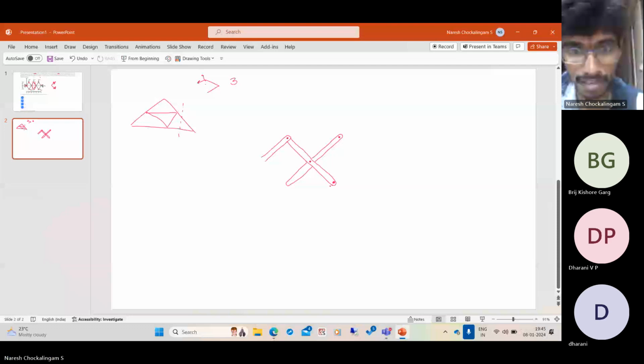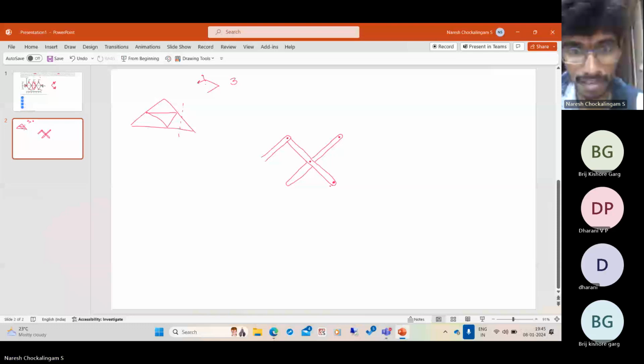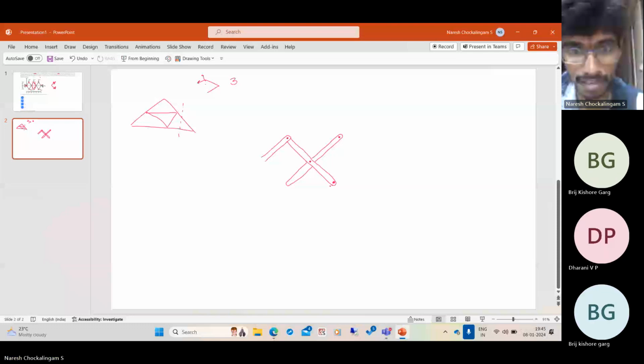So this, the end, these are continuous. That is, this angle is 90 degrees, right? So this is 1 in 1, so this is 45 degrees. So this is 90 degrees, which means unless it deforms, that remains at 90 degrees, or during deformation also, that is what it means if it's a moment resisting connection. But the member as such can be hinged here. That is what it means.